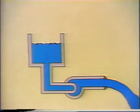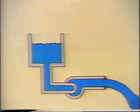Other fluids, such as gases and steam, are compressible and act differently. So keep in mind that what we talk about applies to incompressible fluids only. So far, we've only discussed flow caused by a column of water. But in the plant, flow is most often generated by pumps. And pumps require a certain amount of pressure at the suction.